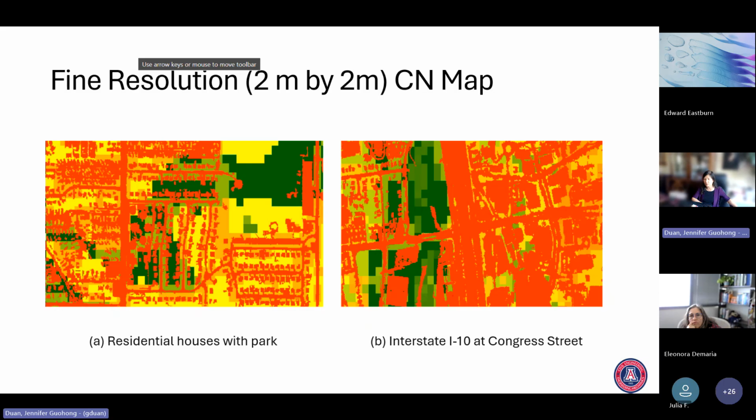But it is important. In fact, we do see runoff on the street ponding in some areas. Just to let you know one thing, we have kinematic wave, diffusion wave, and dynamic wave. Kinematic wave cannot simulate this ponding phenomenon, because kinematic wave is based on the slope: surface water only goes down the slope from high elevation to low elevation.